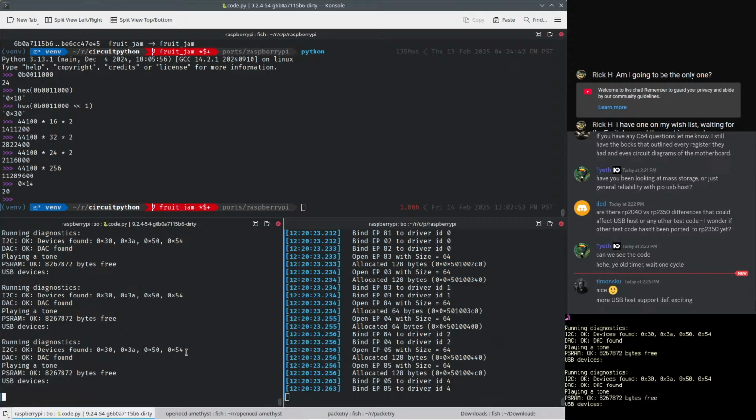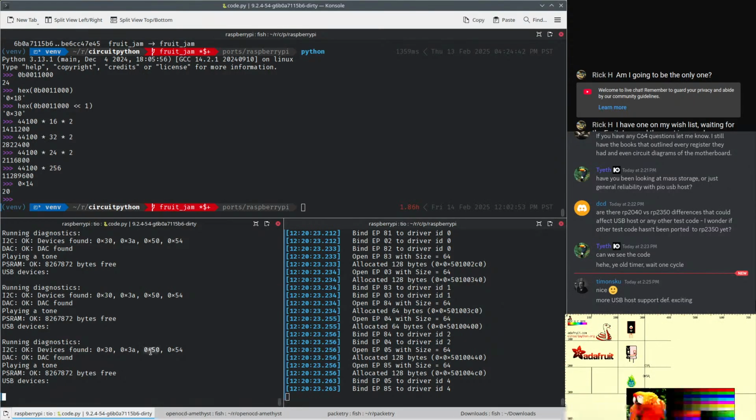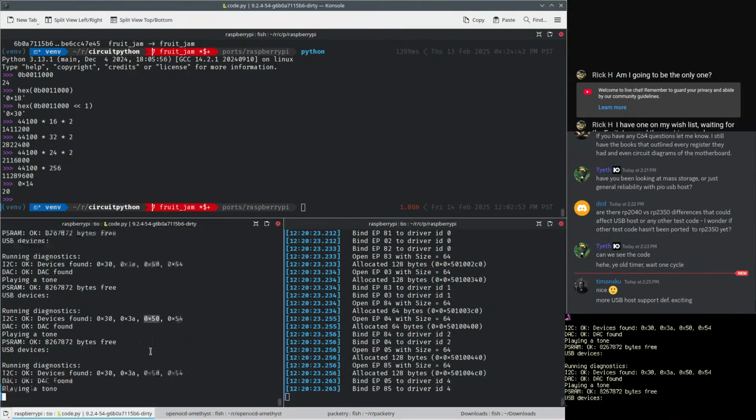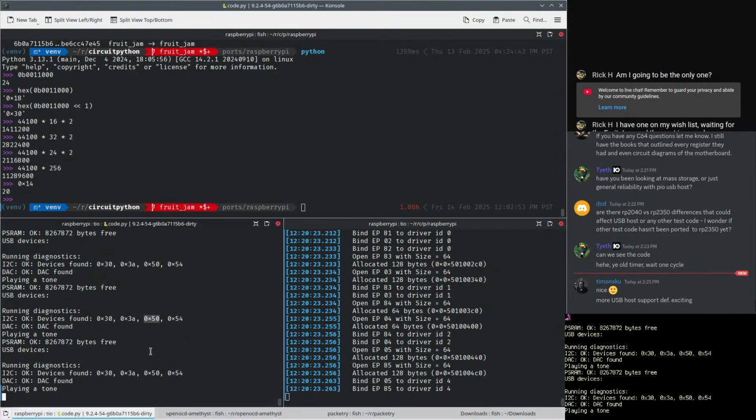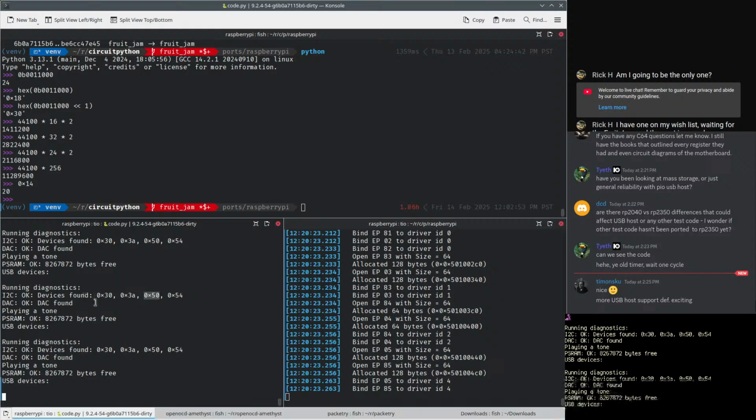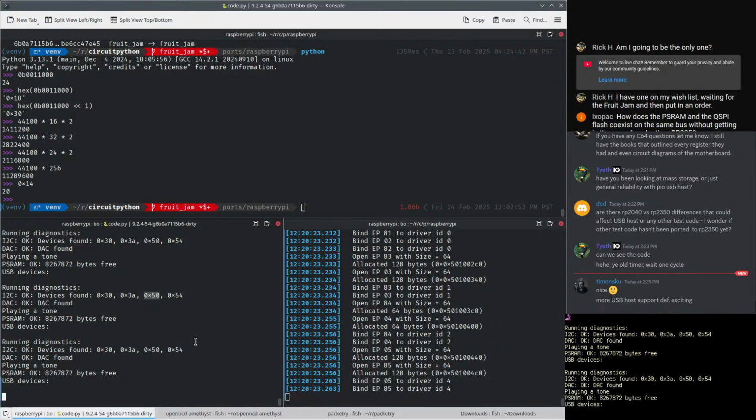It could be that HDMI cables actually carry I2C over them, and this 51 is the one that is how you read the resolutions of the display. So it's possible that the capture card that I'm plugged into has these other devices on the I2C bus. If I plug it into the TV, I only get 50.